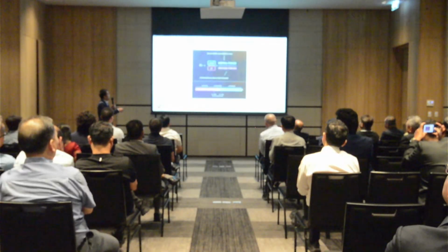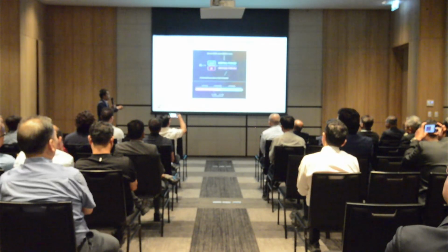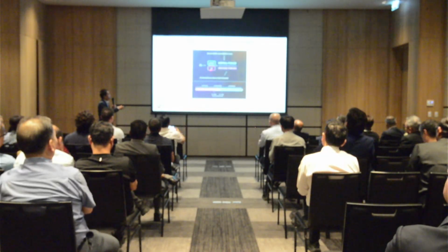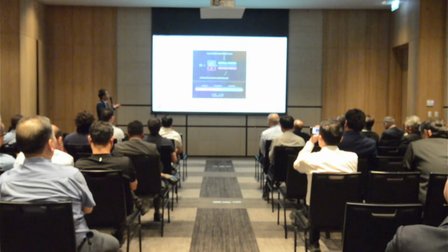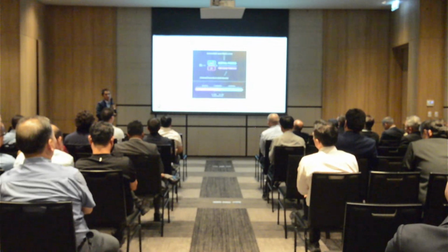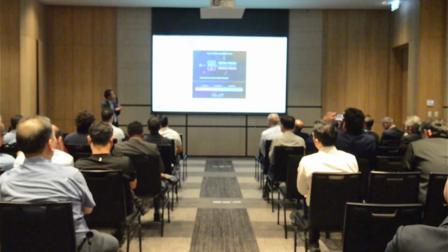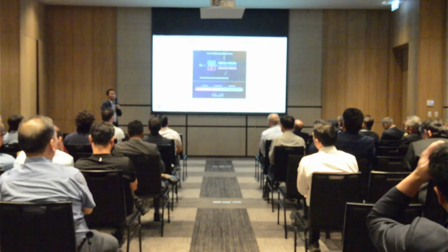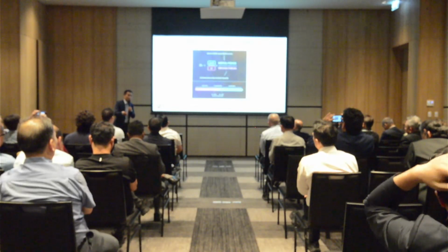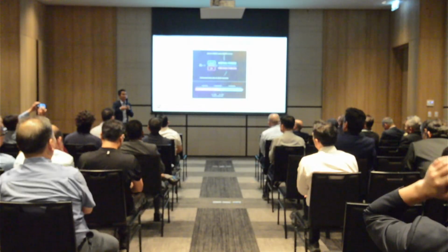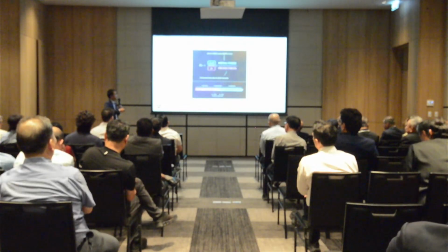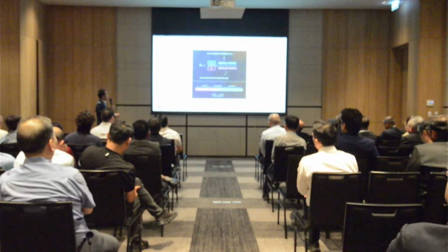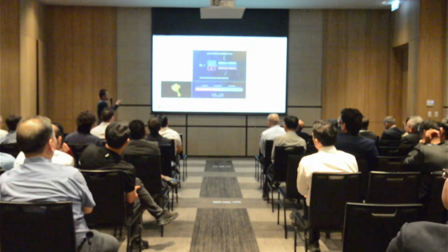In the Reynolds number, this is the velocity, this is the viscosity. For any liquid die cast or liquid casting, we only control the velocity, because it's fully liquid, you cannot change the viscosity. For gravity castings, you cast very gently and slowly, the feeding speed is lower, less than 1 meter per second. It's like a laminar flow. Like very gently feeding, very slow.